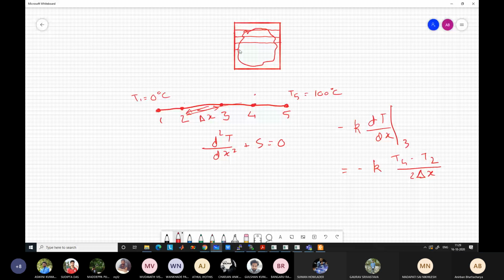For example, if you are solving a conduction problem and you have boundary conditions here, some adiabatic condition, you can assume that these grid points which are outside the domain have zero thermal conductivity, or very small, negligible thermal conductivity, so that although they are solved during the solution of the problem, they do not influence the temperature field because they have zero thermal conductivity. No heat can go out of this wall.